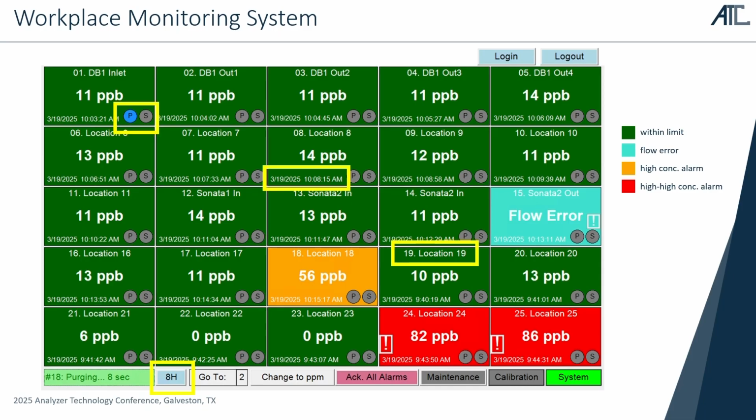You can also change between real-time measurement and 8-hour time-weighted average. The 8-hour time-weighted average is something that's required by EPA for these latest ETO regulations. And you can change between ppb and ppm, but usually it's ppb, parts per billion, because that's the low detection limits that are required for this application. If you're going into ppm, then something scary is really happening.